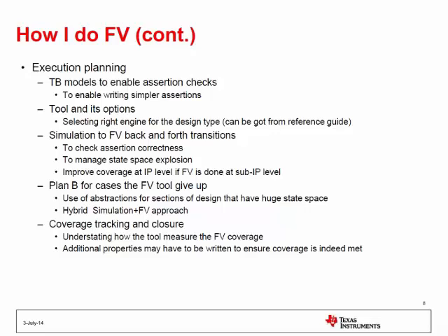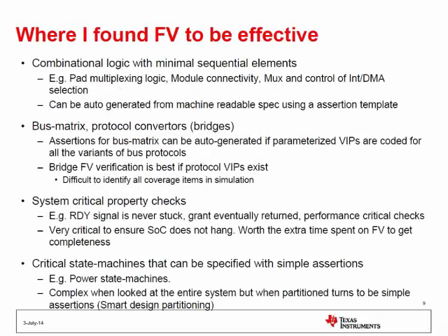This is where, again, I was talking about working with your spec owners to get it in a very machine-readable form. It's a very simple assertion template you can use, and then dump out the assertion that you can just apply there. And module connectivity, again, one of the gentlemen pointed out, right? You can do module connectivity at the SoC level based, again, on a template. You can use IP-XACT to import your pin names and then do a lot more automation on top of it. Mux control logic for interrupt, DMA.